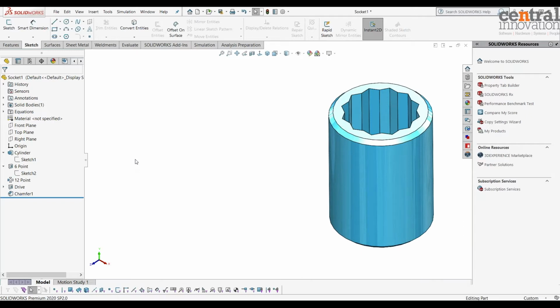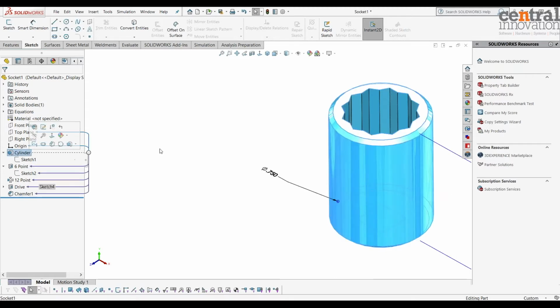Now there are no more things that I want to refer to in the model, just two points. If we can change the name of the dimensions, it will be absolutely helpful when we want to indicate which dimension we are going to use inside the design table, which you will see in a few minutes. And the second thing is that sometimes we need to change our design intent, meaning that, as you could see, the thickness of the wall